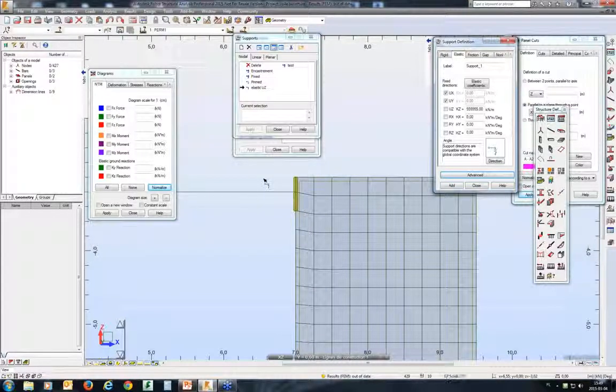All right, and then when we were talking about the node connection being automatically fixed, why would you do the rigid link if the beam wall connection is automatically fixed? Right. It is always the decision, whether you want to have more accurate results or whether you want your model defined in an easier way. Here it is always the situation when you apply a concentrated force in a point location for a shell model.